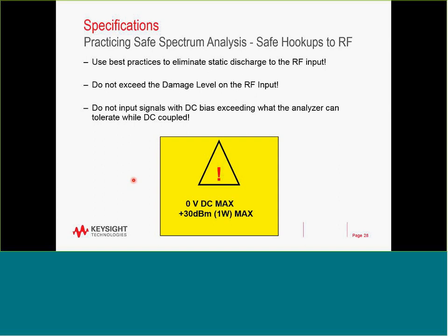Also, you have to make sure that you're not exceeding the maximum RF power. When we say the power is plus 30 dBm, it's wise to plan your test system with a margin of about 3 dB. So you design and you pick the attenuator that you're going to use to make sure that the signal will not, in this case as an example, exceed plus 27 dBm.